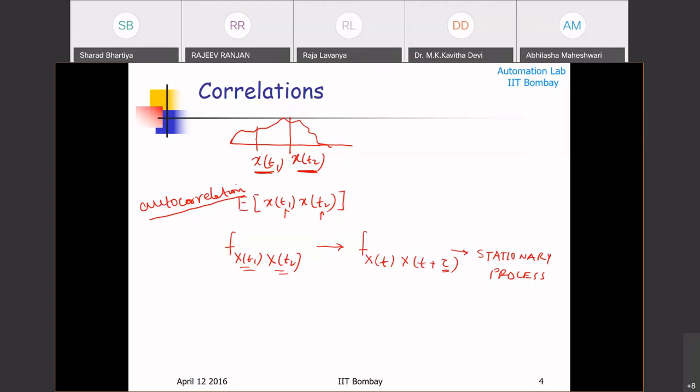So when is it not stationary? If I have fouling in my heat exchanger, there are some things taking place which invalidate the relationship between now and 4 months later. So it will actually depend on when you did that modeling. What was T1 and T2? In that case, you will say the process is not stationary. In engineering, for dynamic systems, you will say it is a time varying system. So you can draw that analogy and think of time invariant systems as stationary systems.